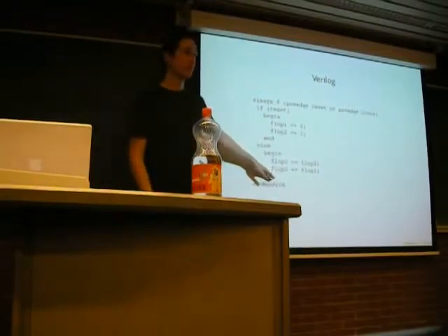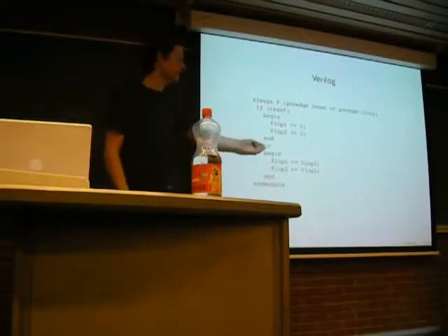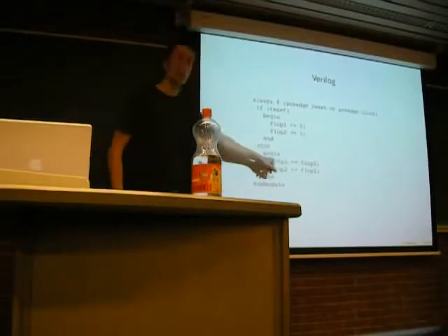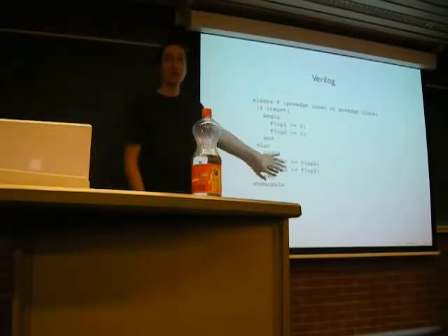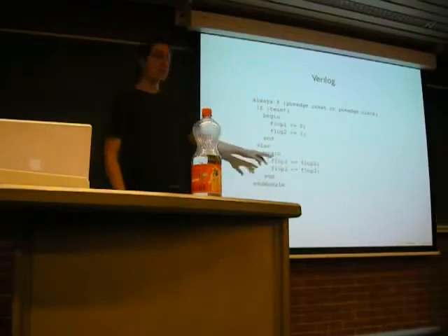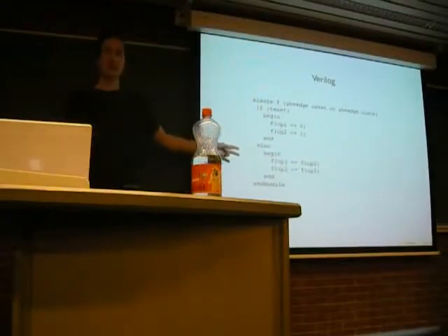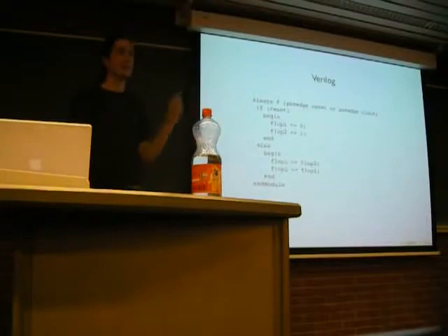Would it change? It wouldn't, it would just stay the same because clock 2 is clock 1 and then stay the same. However, in Verilog, everything goes in parallel, so these 2 will actually swap the registers because they're done simultaneously. This is really the keystone concept of programmable hardware. You can just define parallel parts.